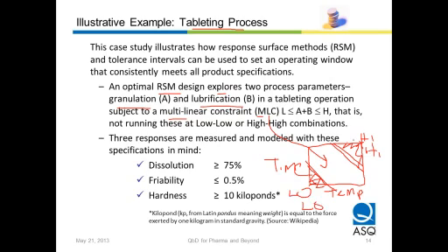Now, as a chemical engineer, of course, I was mostly concerned about this combination of high time and high temperature, because very often it would create an exothermic runaway reaction, which was something you didn't want to have happen. So we are going to impose these multiple linear constraints to frame our experiment to begin with, and then we'll systematically vary the inputs and measure the outputs, which are shown here.